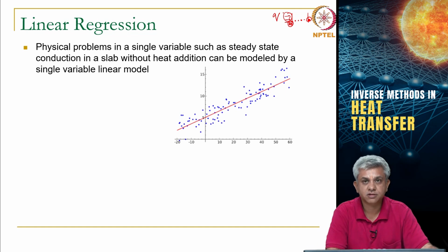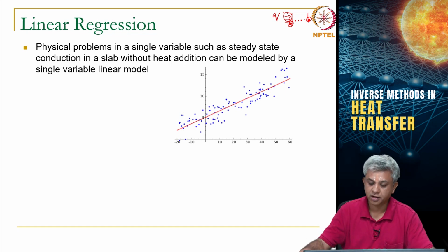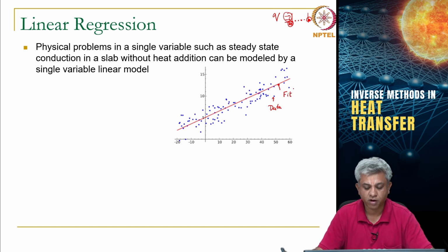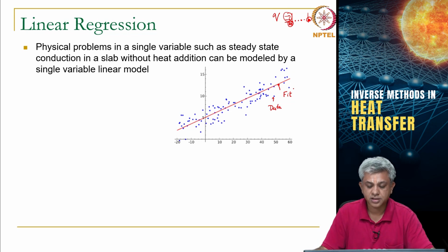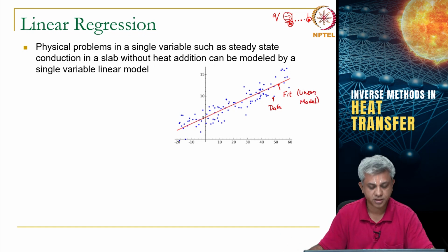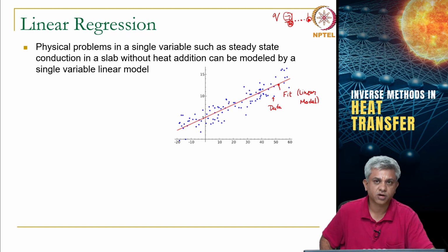Now, in this case, the general problem is that of fitting some scattered data. So, this is the original data set and we try to fit a line. This is the general example of how something of this sort could look. As you can see, a linear model cannot fit all data points simultaneously if there is noise. We will come to characterization of this noise in week 4 and week 5, but right now we have some noisy data. In our case, this noisy data is because of the thermocouples. The sensor might be noisy or there might be other physical effects.